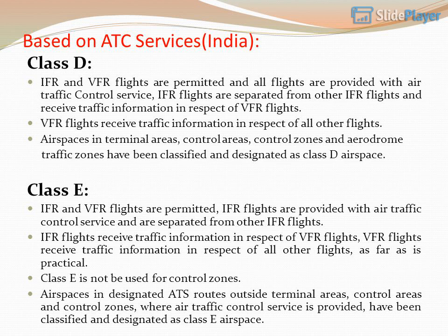Class E. IFR and VFR flights are permitted. IFR flights are provided with air traffic control service and are separated from other IFR flights. IFR flights receive traffic information in respect of VFR flights. VFR flights receive traffic information in respect of all other flights, as far as is practical. Class E is not to be used for control zones. Airspaces in designated ATS routes outside terminal areas and control zones, where air traffic control service is provided, have been classified and designated as Class E airspace.